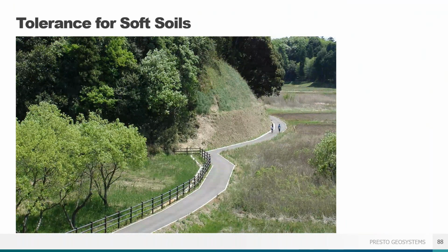Using the GEOWEB system can help avoid expensive and time-consuming activities, such as surcharge loading a site, which often has to happen when differential settlement is a concern. The time required for the surcharge loading may be reduced or even eliminated when using GEOWEB walls. It also reduces the amount of visual inspection, maintenance, and repair over the lifetime of the wall structure, since the GEOWEB panels can accommodate much more movement than a masonry wall.